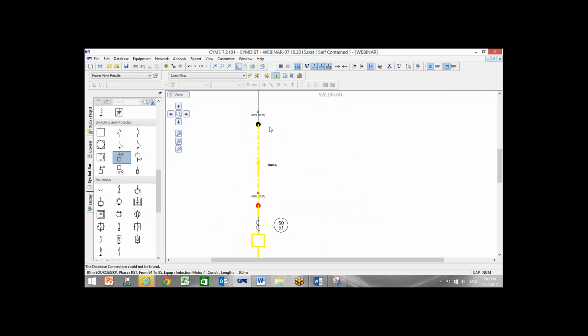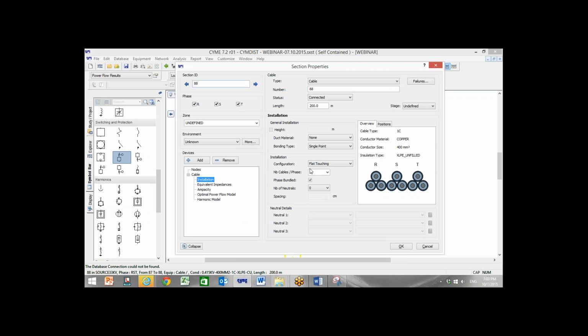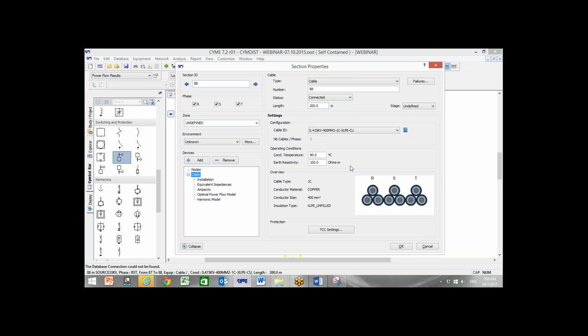Now you can see the voltage here 0.97, but this cable, the current passing this cable is 2968. So this cable cannot withstand this. And the cable is 3. Let's put it 4 in. Or the length maybe is, I don't know the length, let's check it. And the cable here is 400. That's it.